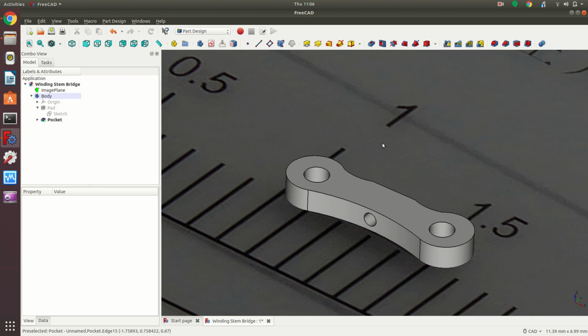Well, actually, we could draw that the screws are sunk in here, but it doesn't really make a lot of sense. We're just going to do that with a conical burr, and this isn't CNC. We just go on top with a conical burr and do that by hand. It's not worth machining that. I mean, we could, but then it's a tool change in the tool path or whatever. So we can say we're done here and save it.